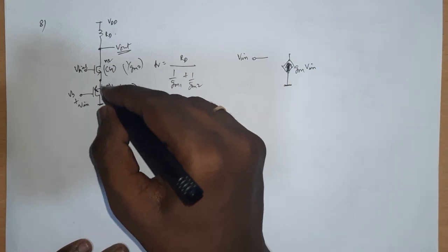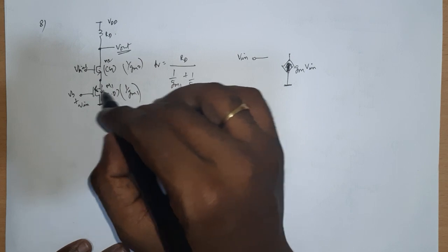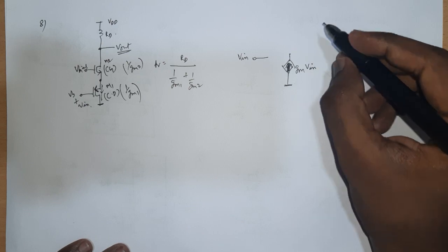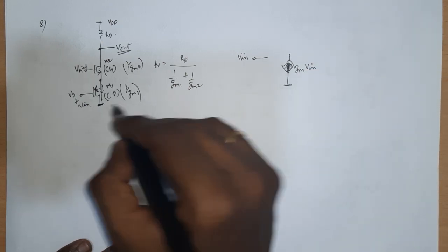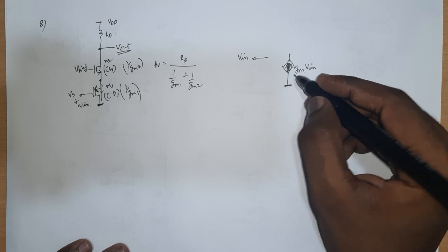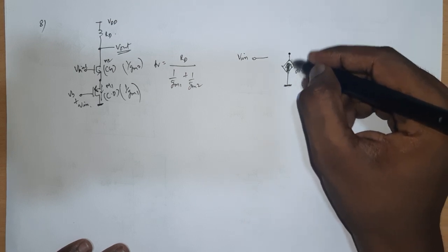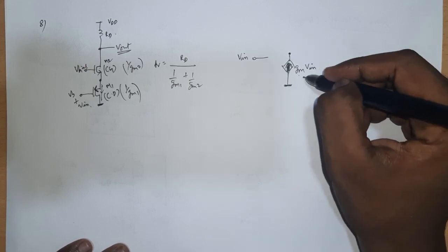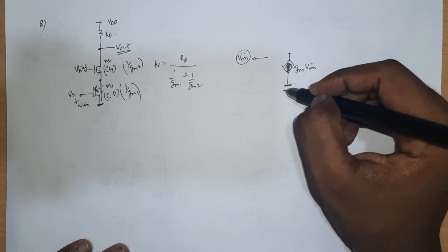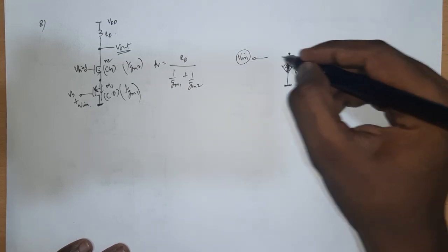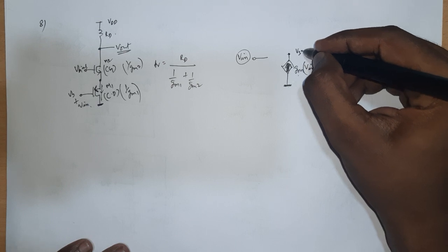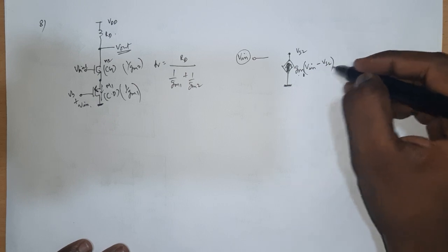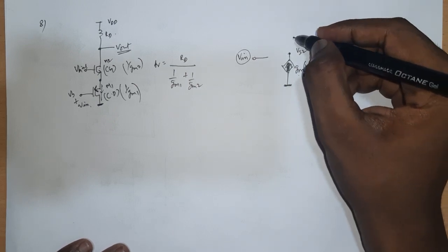Although from source to drain I have my DC current, as far as the PMOS or NMOS is concerned, incrementally they are the same. So incremental current always flows from drain to source, and the PMOS drain is connected to ground. From drain to source, this is the source terminal, I have a current that is gm times VSG. Sorry, gm times VGS. So VG is Vin and S is this terminal, let's call it VS2. So gm1 times Vin minus VS2.